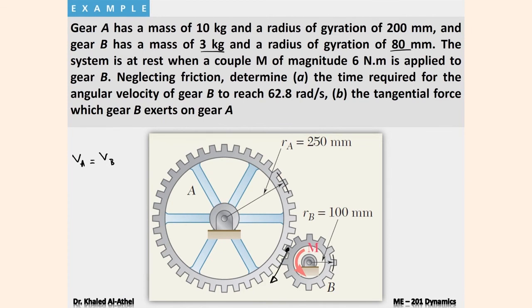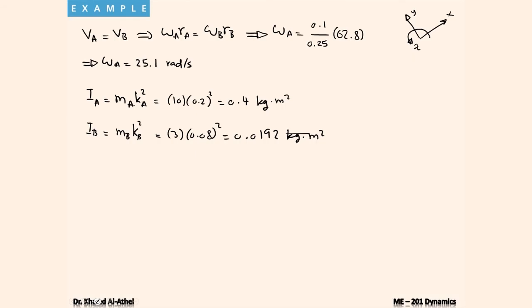So this is acting from B on A, and A has this effect on B. So I'm going to put this as a force BA, from B acting on A. And I also have two reactions in here, AX and AY. So these are the forces, and this should equal the final angular momentum, which is IA omega A2, something like this.